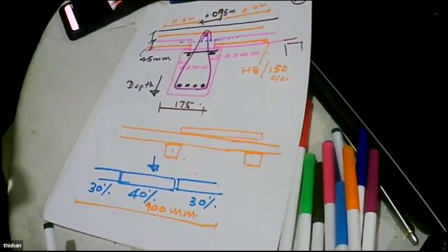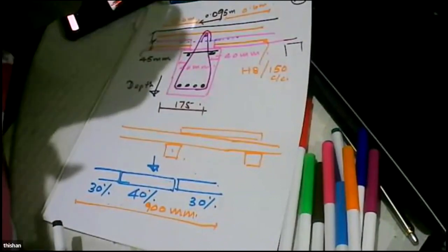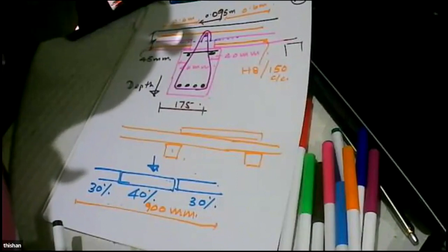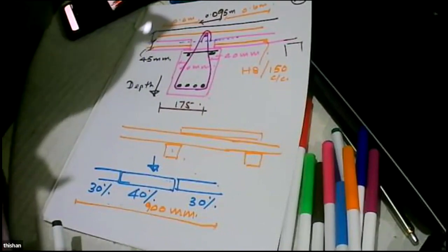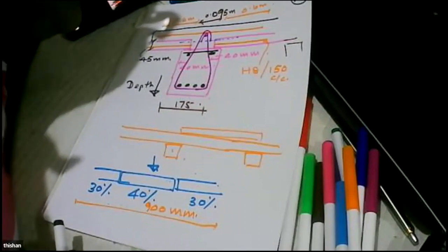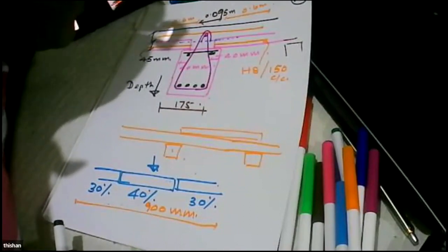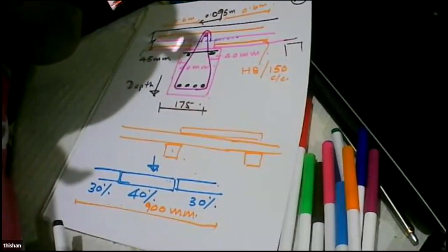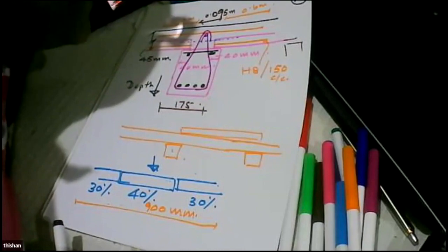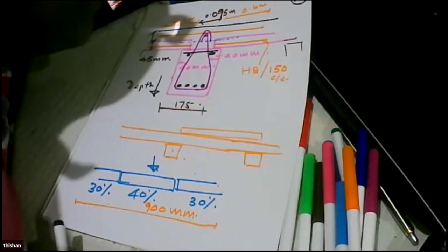There's one question asking whether we can use pre-stressed beams. Yes, you can, but these are low technology systems done with high technology, like high strength concrete. We want to make sure that without a big investment, you can cast the slab on ground. That's why we don't go for pre-stress, but pre-stress also can be used. Okay, clear, sir. I think the questions are over.